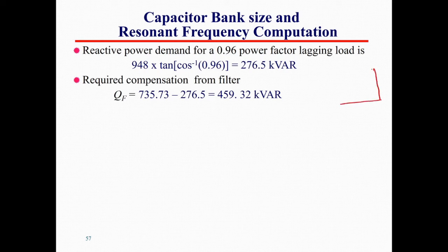improve the power factor. So again, this is P, this is the initial reactive power, this is theta 1, right? And now we would like to improve the power factor, as he told us, to a smaller angle. Therefore now we can calculate also what will be Q2, right? And the difference between Q1 and Q2, that will give us the Q for the filter.